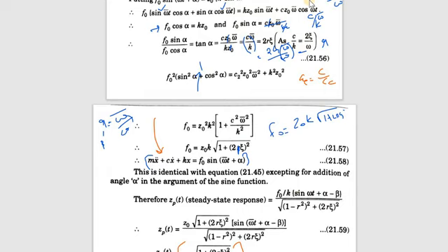So theta is equal to C by Cc, but Cc is 2m omega. Now instead of m I am changing it, since I don't have any m term here. What is omega? Omega is equal to root of k by m. So omega square is equal to k by m, so m is equal to k by omega square.